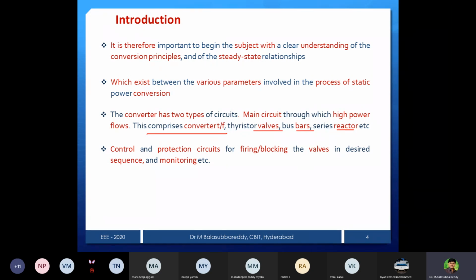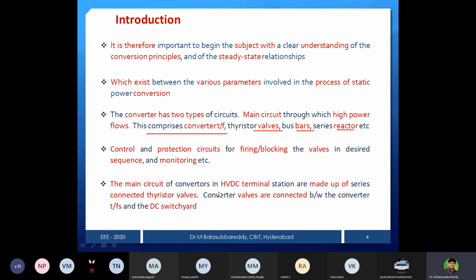If you are aware of the 3-phase full control rectifier, we mentioned there that the positive group devices are 1, 3, 5 and the negative group devices are 4, 6, 2. In that aspect, we can observe that the sequence of conduction is 6-1, 1-2, 2-3, 3-4, 4-5, 5-6, and then the 6-1 cycle is repeated like that. So this will be monitored. There is a desired sequence as well as the conduction.